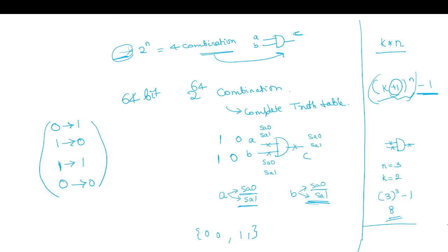Now let's do this math manually. Either all the 3 can have a fault, that will be 1, or just these two having a combination of fault. Like all the 3 can be stuck at 0, or all the 3 can be stuck at 1.